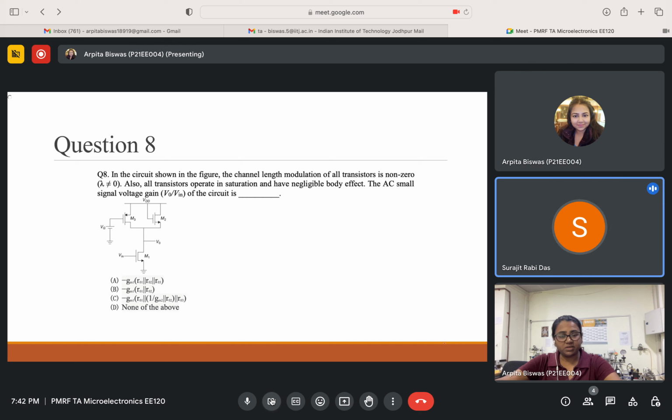Yes, because in the device I am now discussing some of the cleaning process. If there is a silicon wafer and there are some organic or inorganic particles, which type of cleaning process are you going to do? Some standard cleaning process. Have you heard about the Piranha cleaning process? No, I don't know. There is the Piranha cleaning process, RCA1, RCA2, the standard cleaning. This is called the standard cleaning process.